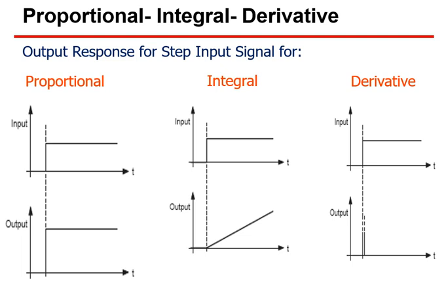One important thing you have to do is take any sine wave and see how the integration of that sine wave comes out graphically. Take any triangular wave and take the integration of that wave. The same concept should be applied to the derivative circuit as well. Apply a sine wave, a triangular wave, a square wave, and see how you get the output.